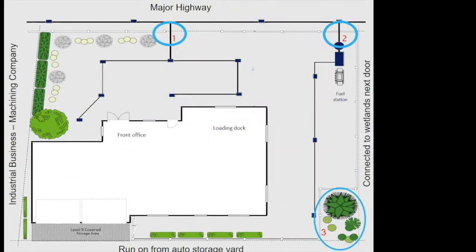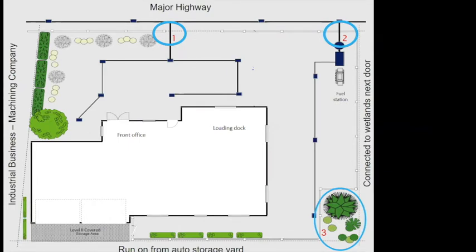And then the last one, we talked about that wetland and how we want to make sure that your runoff isn't running into the wetland that is off your property, and that it's bermed, so your stormwater is bermed so that it goes into the catch basin. And so we need to make sure that that is happening. If it is not, if you have sheet flow that is going into that wetland, that would be another discharge point that you would need to sample.